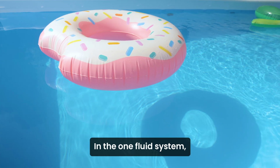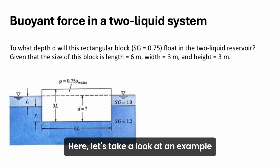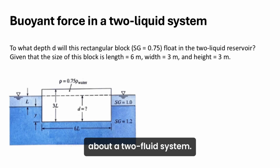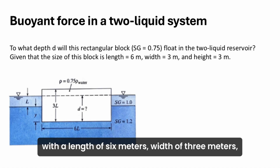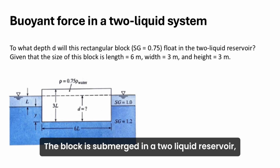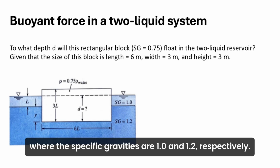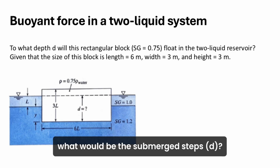In a one-fluid system, the calculation of buoyant force is usually straightforward. Here, let's take a look at an example about a two-fluid system. We have a rectangular block with a length of 6 meters, width of 3 meters, and height of 3 meters. Its specific gravity is 0.75. The block is submerged in a two-liquid reservoir, where the specific gravities are 1.0 and 1.2 respectively. Referring to the figure, what would be the submerged depth, d?